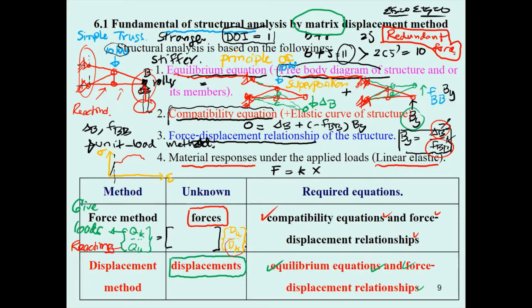This is the displacement at the support of the truss. This is the reaction; the reaction is the force at the support of the truss. See? And then what we have inside needs some kind of derivation. We will go to this derivation later. But this matrix is called the stiffness matrix. Okay, it's called the stiffness matrix.